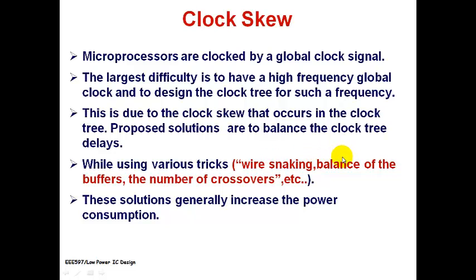And in some cases, I would go for adjusting even the buffers. I may want the clock from here to reach a longer path there, and there may be a much shorter path. So here I have a unit 1 and here I have a unit 1 and 2, and I will have these two supplied by the same clock source without any skew.